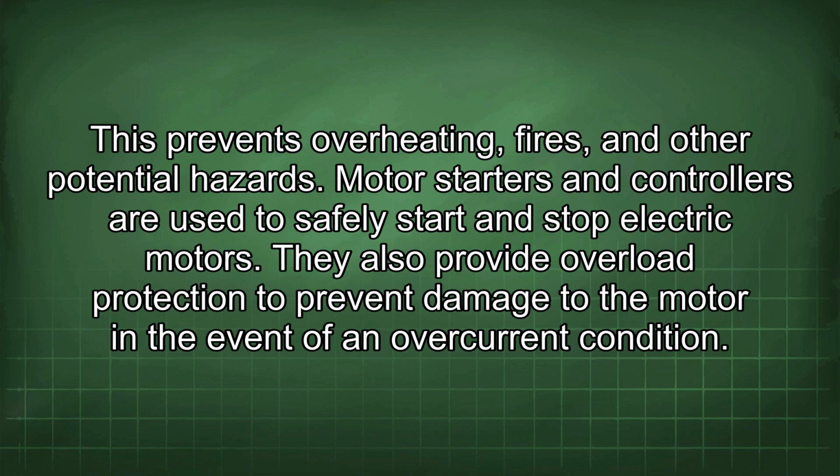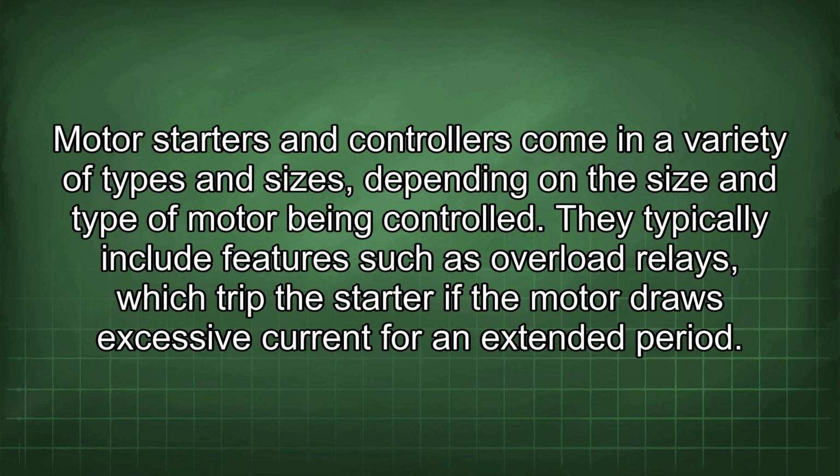Motor starters and controllers are used to safely start and stop electric motors. They also provide overload protection to prevent damage to the motor in the event of an overcurrent condition. Motor starters and controllers come in a variety of types and sizes, depending on the size and type of motor being controlled. They typically include features such as overload relays, which trip the starter if the motor draws excessive current for an extended period.